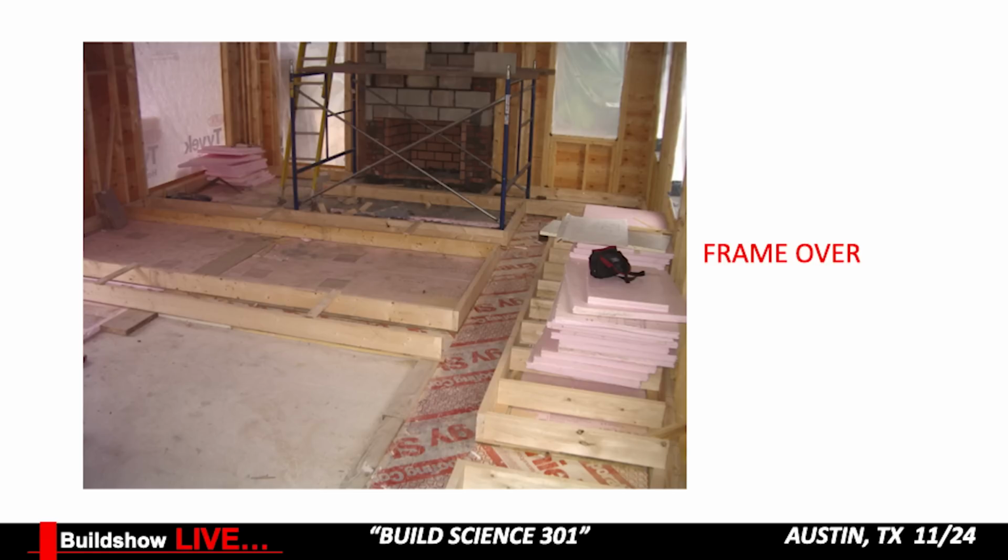Frame over. These are all, you know, like I said, been doing this a long time. Matt and I shared a bunch of photos, but pulling some of these out that are just different generations, different variations, maybe a few steps outside of the box. Remember why we're here, right? So this is what I called the frame over. We actually framed a 2x floor over. Notice we had the HVAC guy come in and he laid out his ductwork on the slab, and then the framers came in, put insulation on top of the slab, and we gave those troughs for the HVAC guy.